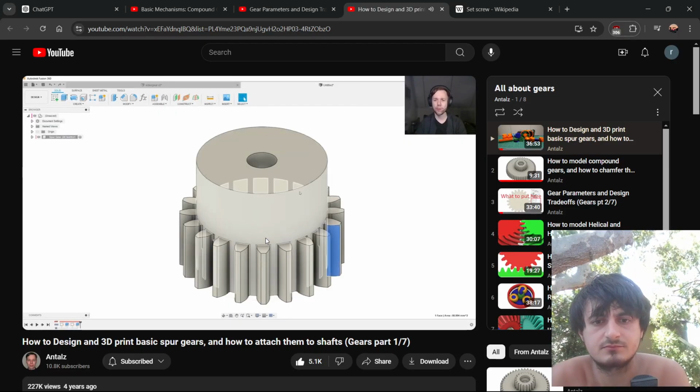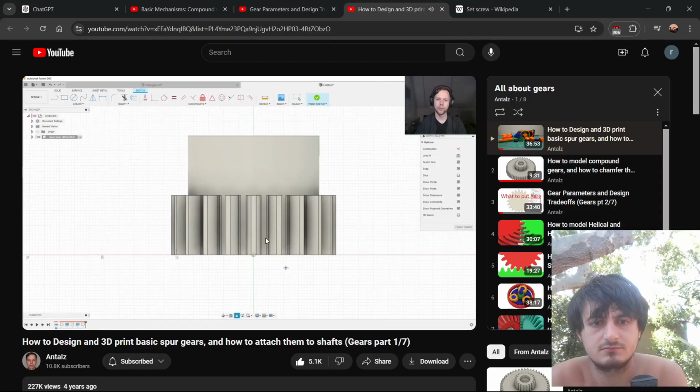We're now back in Fusion 360, and I've already designed some features of the gear. So the teeth are already there, I've already made the mounting hub, and I've already made the hole for the shaft. In this case, the hole for the shaft is 10.2 millimeters, because I want to mount this gear on a 10 millimeter shaft. What I'll do now is create a sketch, and hit one of these vertical planes. I hit P for project.